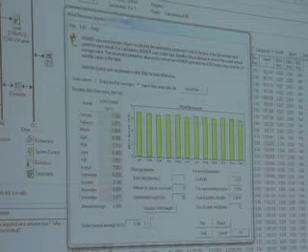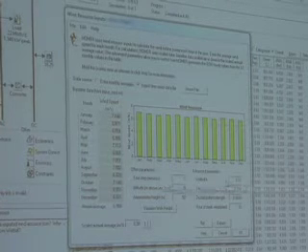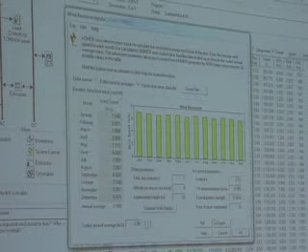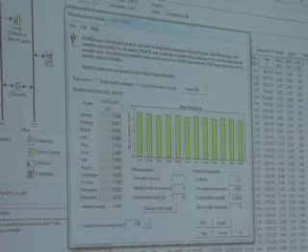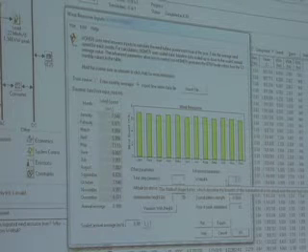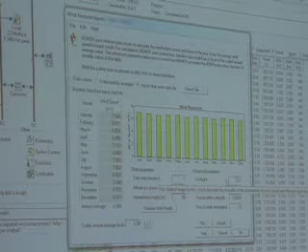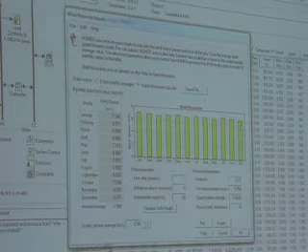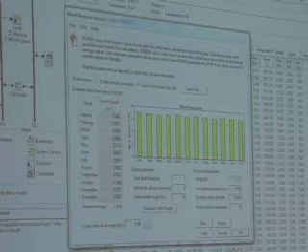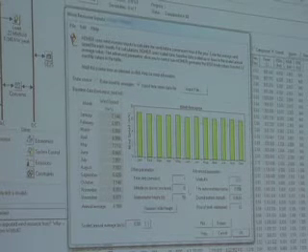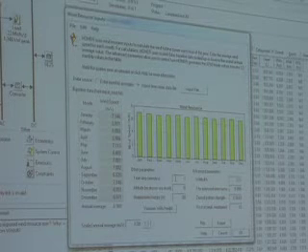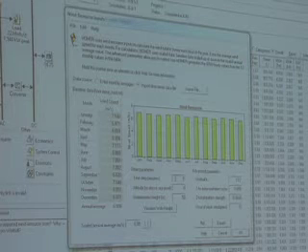So let's talk about the, and then if you import the data, Homer will calculate these parameters. So this was a trade wind regime. A Weibull K of 3.72 is really exceptionally steady wind. You can see there's almost basically no seasonal variability. Autocorrelation 0.956 is exceptionally stable. It's got 1 minute time steps, so you'd expect the autocorrelation to be higher for short time steps than for longer time steps.